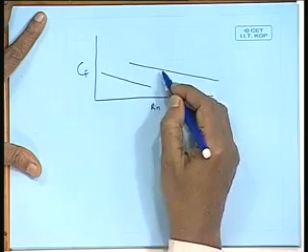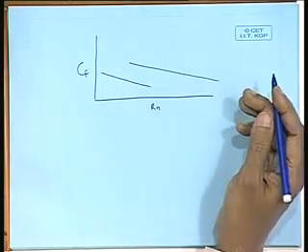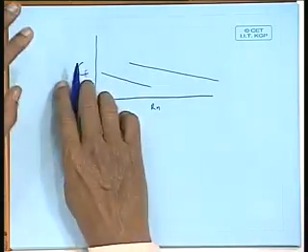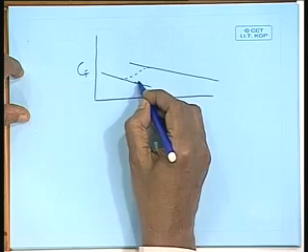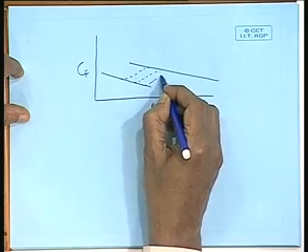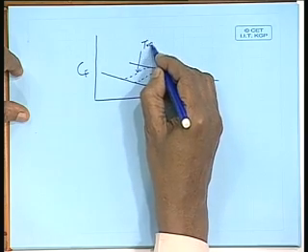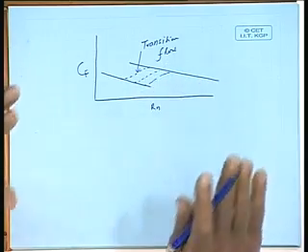And how do they match? How does the CF catch up? It should be a continuous curve. You can see this overlap region is a region where both laminar and turbulent flow stays. That is, laminar flow changes to turbulent flow over a region of Reynolds number, and this is normally called the transition flow, like this. Transition flow depends on local conditions.